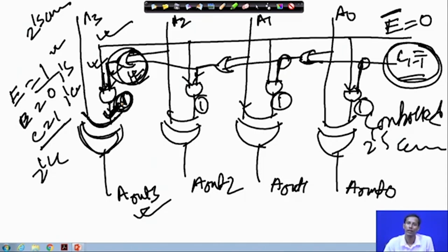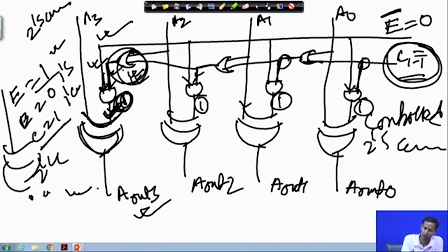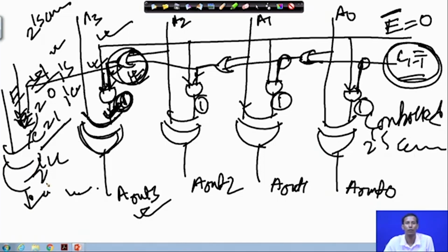This is for 4 bit; for n bit this particular position will just continue, and at the final stage we will get these values here, an n gate, and that will be ORed with the carry in generated from the OR gate, and then that will be ANDed with the enable signal, and you can get the corresponding n bit sum output, sorry, this 2's complement value output.